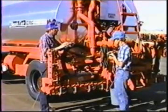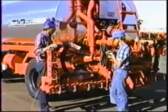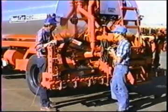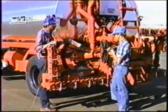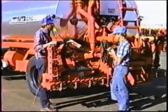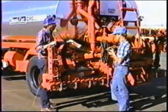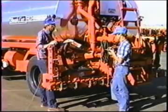What that tells us is that if we drive at a speed of 400 feet per minute, regulate the pump speed to 135 gallons per minute, if we turn on 12 feet of spray bar, that'll create a spread rate of 0.25 gallon per square yard.